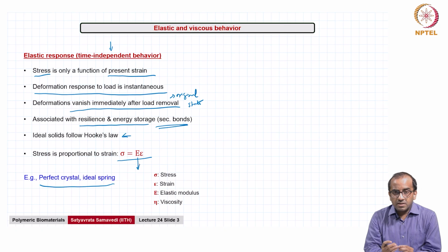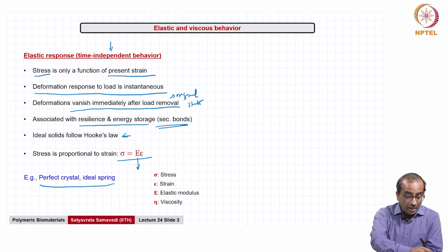One way to think about it is the ability of the material to resist deformation, right. So, the key here is that load and deformation are related through the elastic modulus. Now, this is the case for purely elastic time independent responses. Now, when you look at the other aspect of viscoelasticity, which is the purely viscous behavior, that is when time comes into the picture.